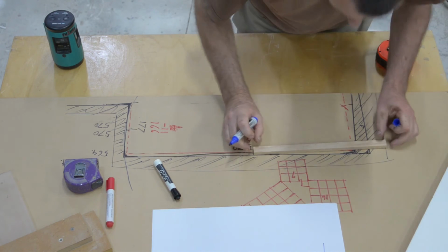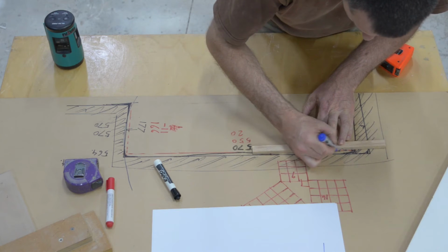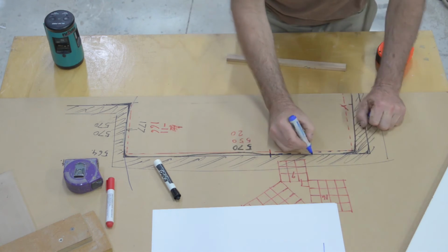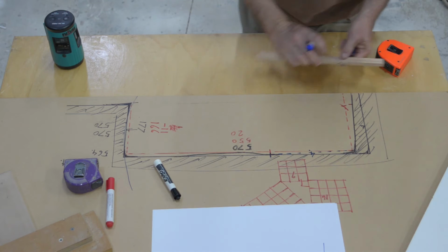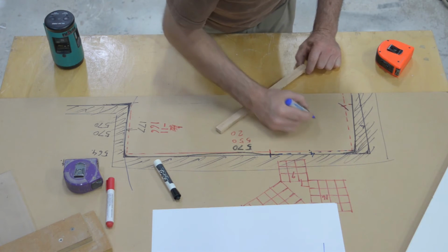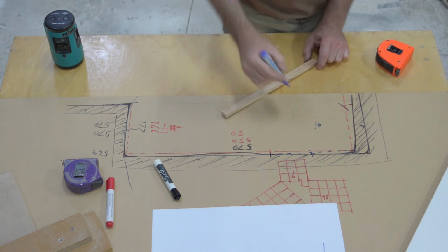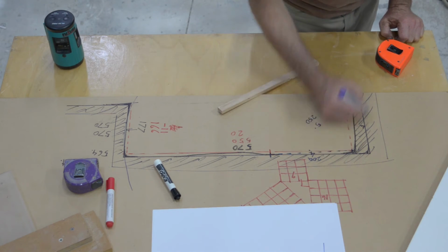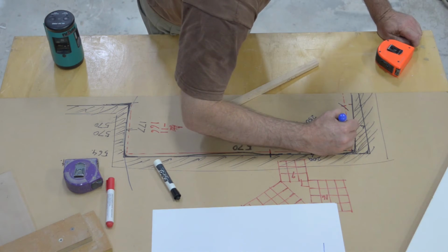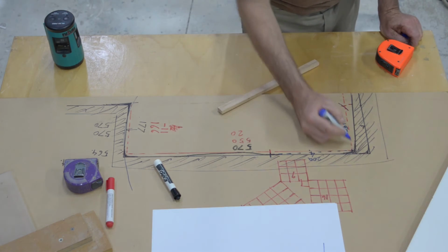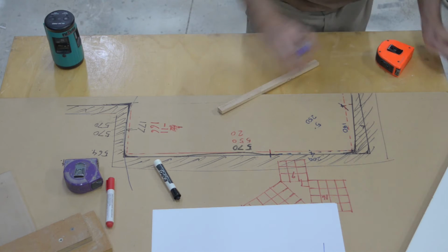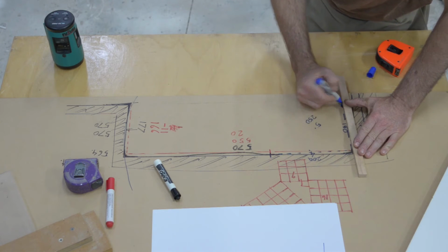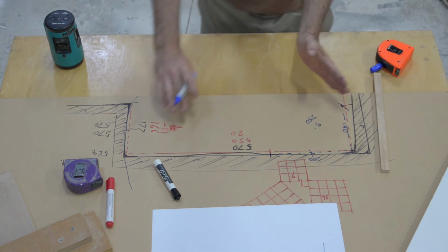I'll do that in blue so it's clear. It's actually quite good that this worked out this way. So there's our 4 side of the triangle. Then I produced this arc of the 5 side, which in my case is 250 millimeters by 200. Now we come out from that same point, 150, which is 3 times our 50 millimeters, and it gave me a point over here. But as you can see, what that's done is, even though I think I've made a square line, I've made it square to this portion. I haven't made it square to the whole line.